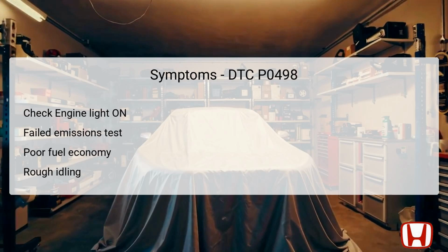Moreover, the malfunction could lead to poor fuel economy as the engine struggles to operate efficiently with unregulated fuel vapor levels. In some cases, drivers may experience rough idling, indicating that the engine is not receiving the proper fuel-to-air ratio as a result of the vent shut valve's issues. Being aware of these symptoms can help in early detection and repair.